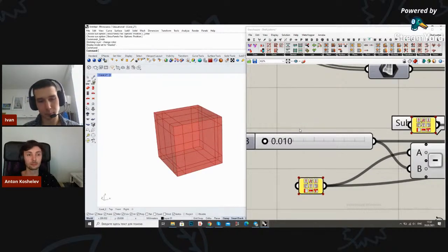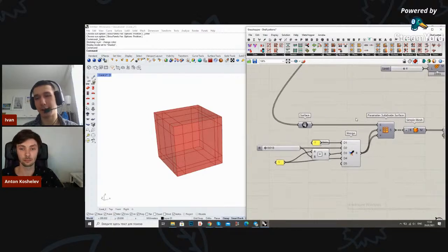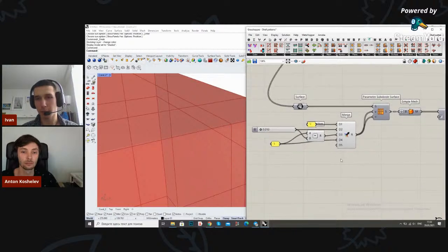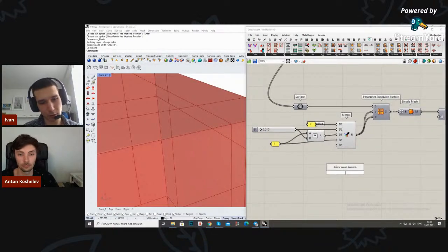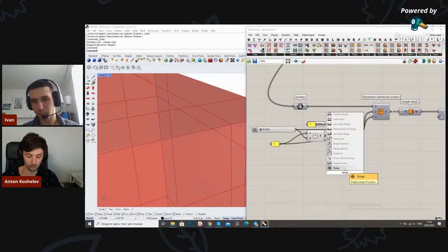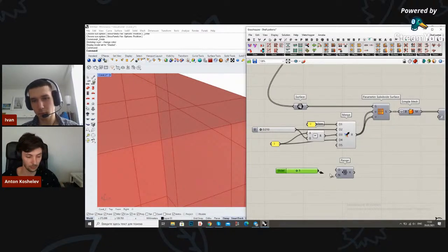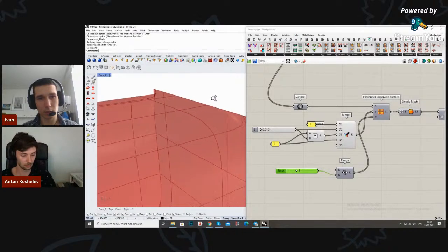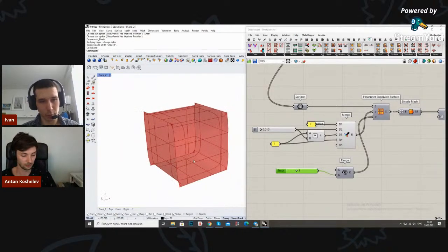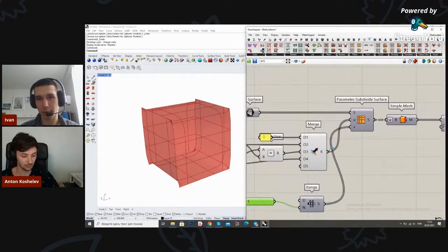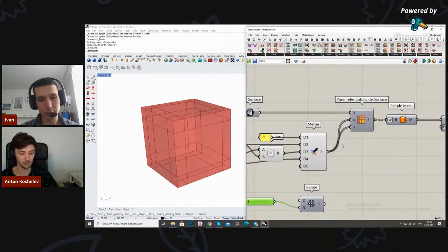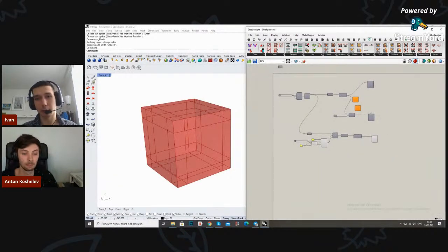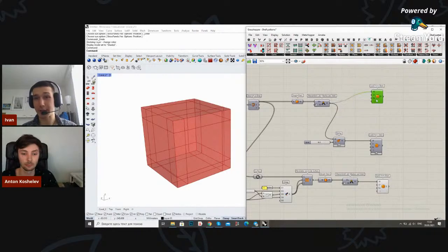And the most important thing is that you see we always need to have these points matching, because I'm just going to give you an example. Let's see. If there is a mismatch happening somewhere, you see what we get? We start getting a very weird and topologically incorrect mesh. So that's the thing you need to always take care about and always need to take into account. Yeah, basically that's it for the first exercise.